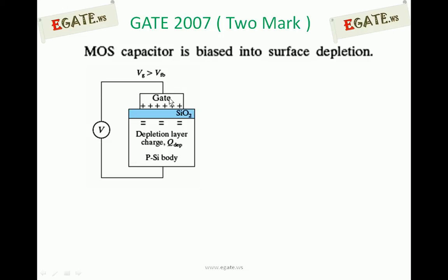If we don't apply any voltage, the majority charge carriers present in the channel are holes, because we are dealing with a p-type substrate. Whenever we apply a small positive voltage, it is able to attract a small negative charge from the substrate. Negative charge in a p-type substrate is nothing but electrons. That is, minority carriers in the substrate are negative charge carriers that will be attracted towards the channel region. But holes are already present at 0 gate voltage.